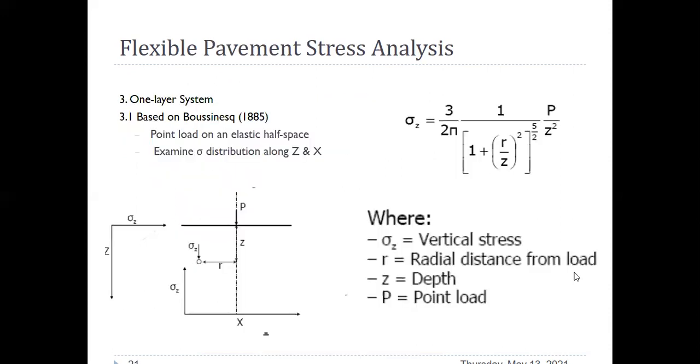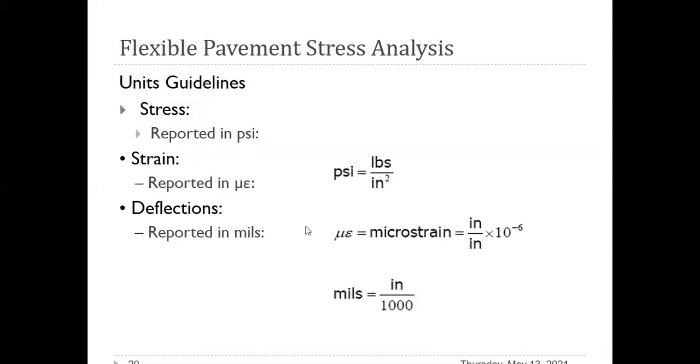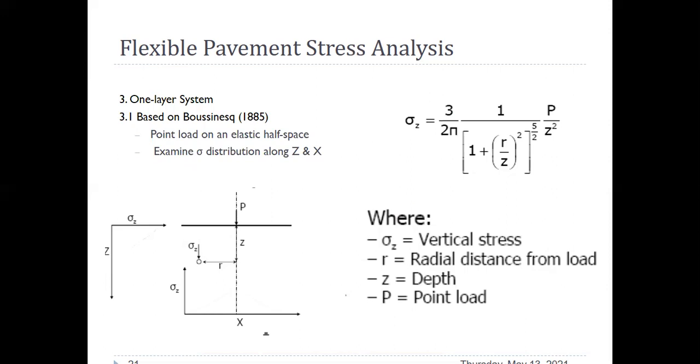Over the years, there have been different theories, and based on different theories, the stress can be calculated. The first theory is called elastic half space, in which we say no pavement exists, and the load from the tire is directly transferred to the ground.